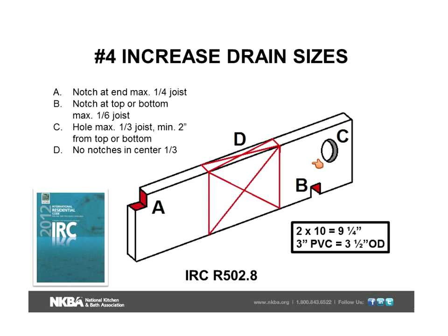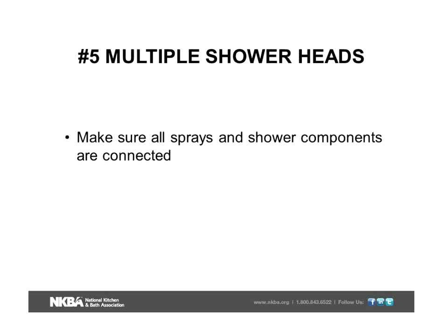So we would have to run parallel to the joist. Not only that, we cannot make any holes within the center third for structural reasons, obviously. So think about this when you're relocating that shower and you're adding all of these body sprays.